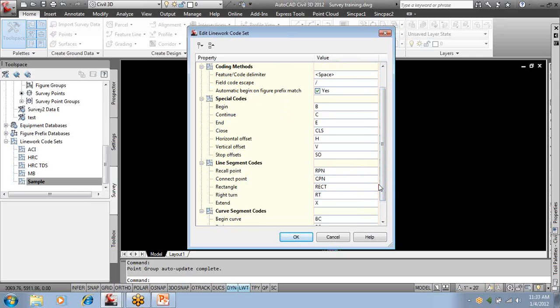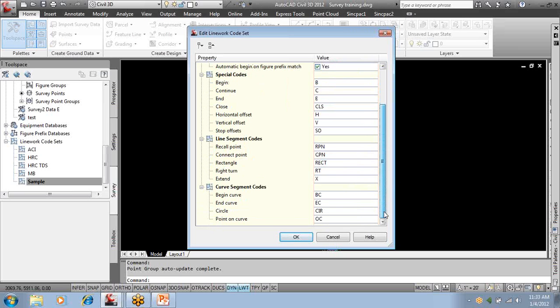So if I'm running one line of curb, it will automatically run the gutter, the top of curb, and back of curb for me. Some of my favorites are now when you run line work on curves, you can begin the curve. You can go shoot anything else that you want to, come back, take another shot on the curve, and you can have as many points as you want on the curve. Before, we had to use C3, and you had to only use those 3 points on the curve, or multi-curve start, and use all those points, and then multi-curve end. So now simply do BC, begin your curve, take as many shots anywhere you want, as long as you're still shooting edge of pavement 1 or that description doesn't change, it does the curve.